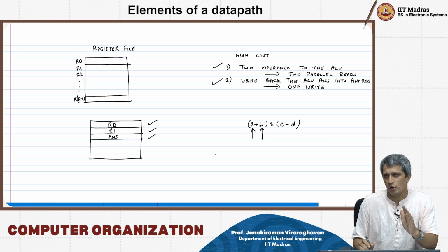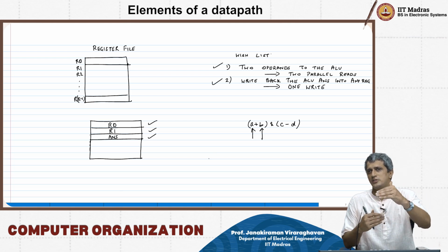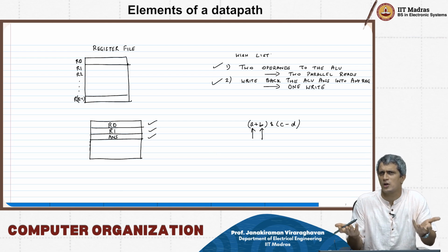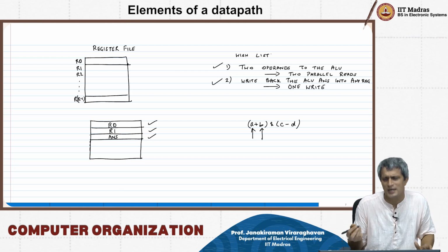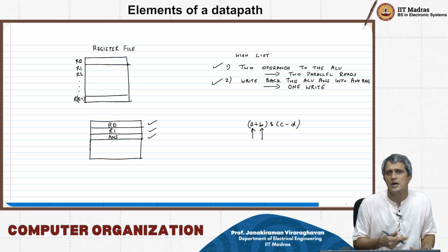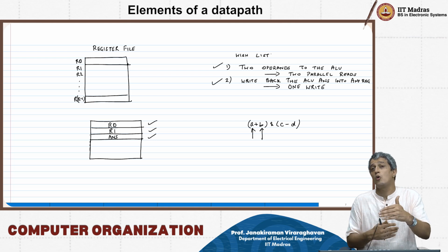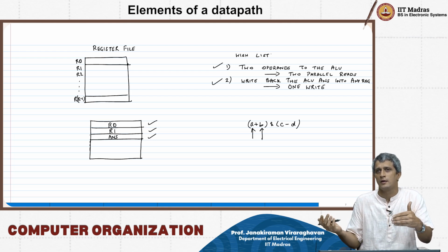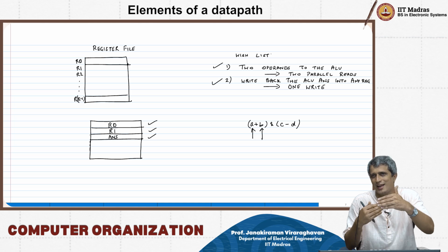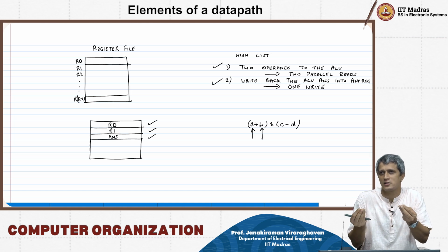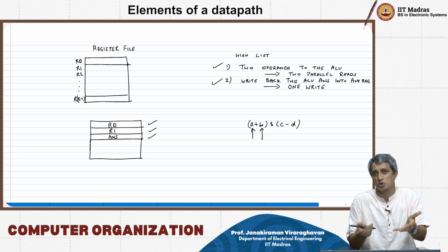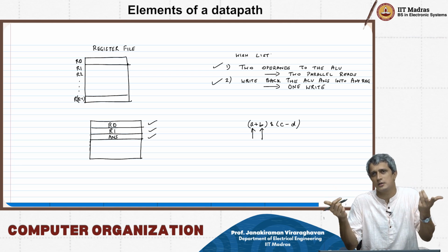But other microprocessors can expand this register list to something like 30, 31, also it's 32. It's not that difficult for you to implement the register file because it's not going into some MB or KB, right? It's actually just a bunch, like maybe 30, 40 registers you might use at most, and each of them is a 32-bit register.